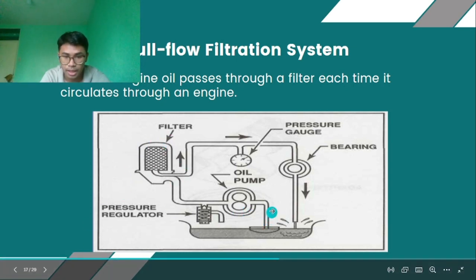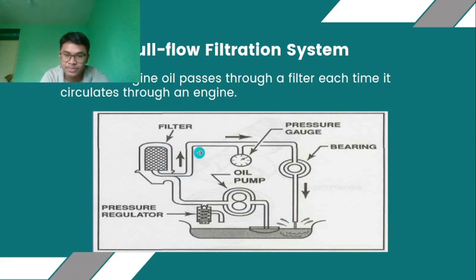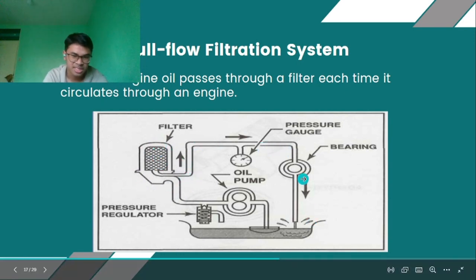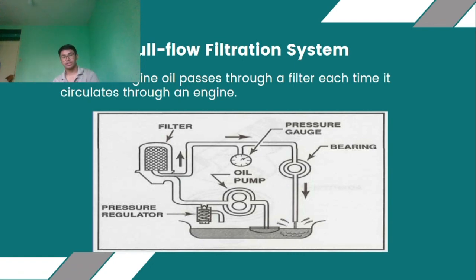So, it is connected to our lubricating system, or it is here. Here, this is our filter. So, after the filter is the pressure gauge, then lead bearing, then back to our tank. So, 100% of the oil flows through our full flow filtration system.